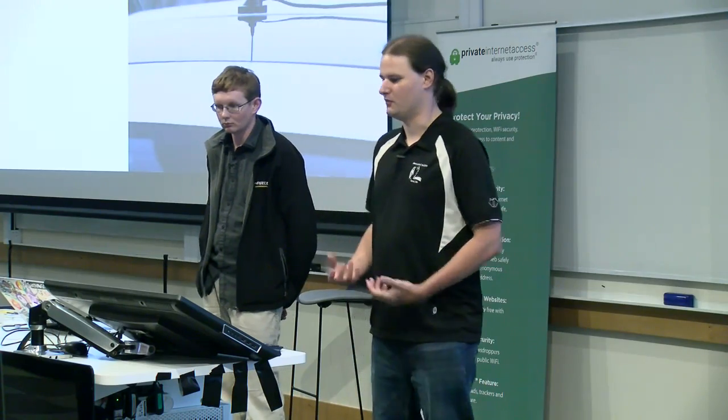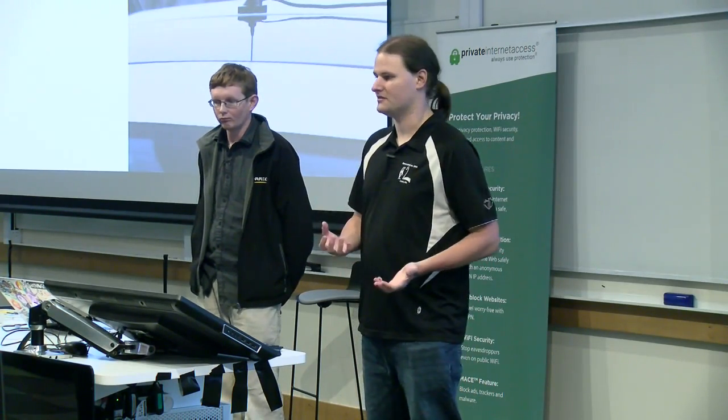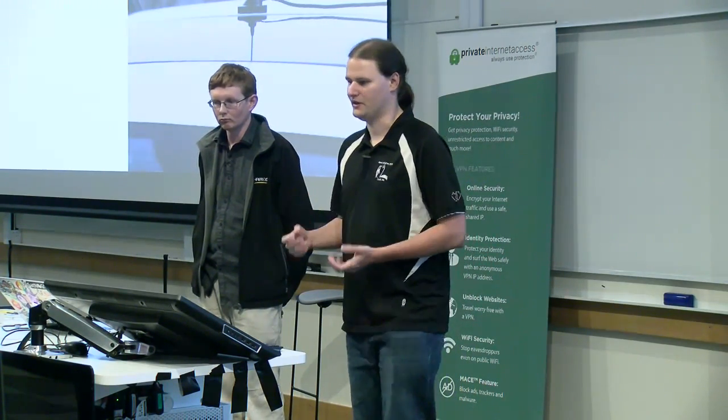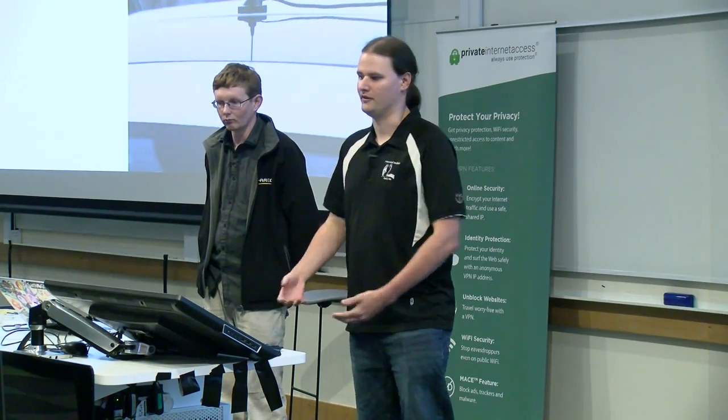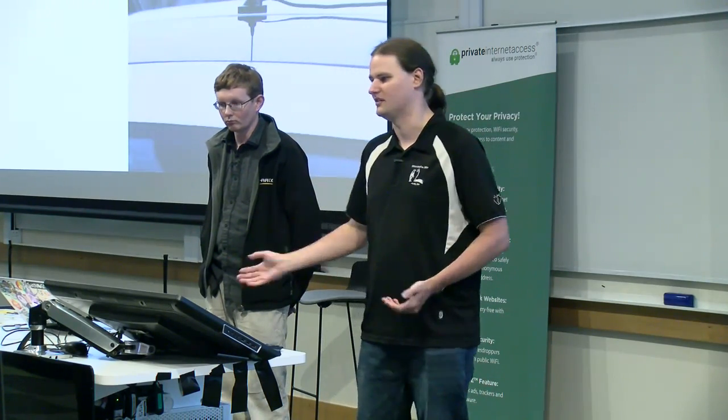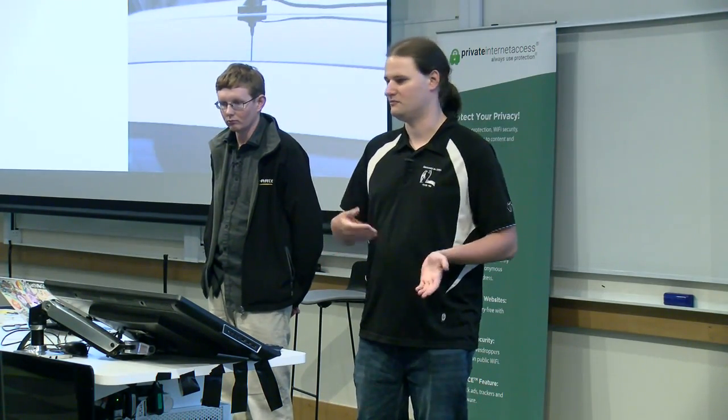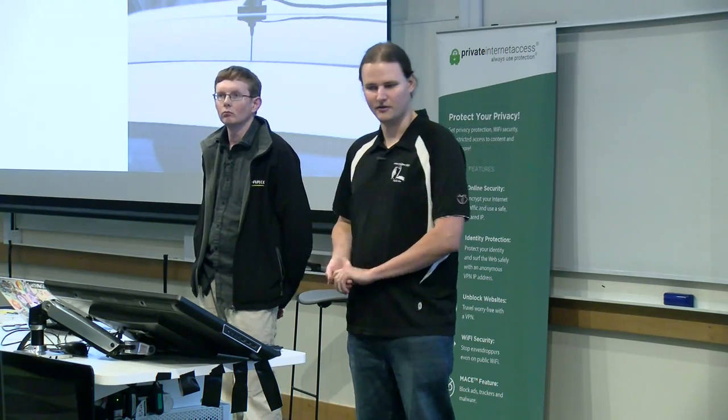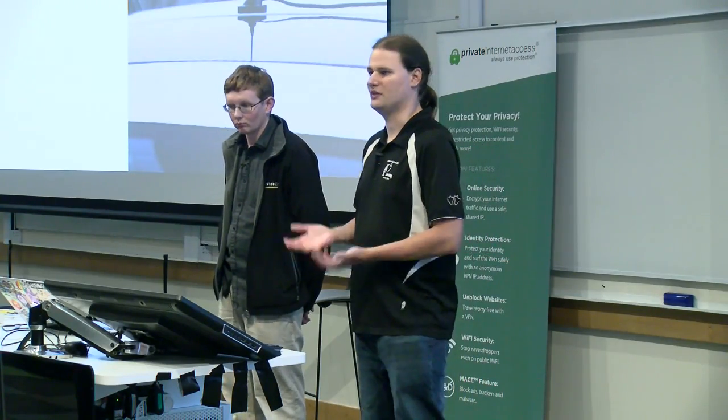The reason why we want to take AutoRX into the vehicle we're going to chase with is you want to try and get the GPS location at the lowest possible point on the ground. If you are running it at home, it's likely that the radiosonde will be below your radio horizon and you won't see the last couple of packets it sends out. The other thing is you need the predictions because otherwise you'll just be driving in a random location. So you can either use SomeHub online if you think that cell phone reception is going to be great, or you can use the Chase Mapper application that Mark just showed us.